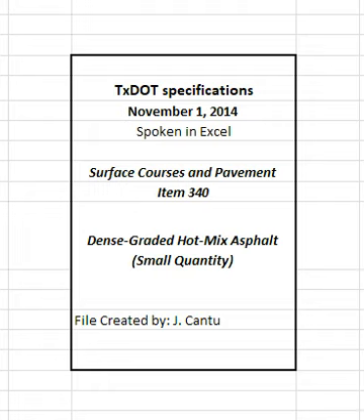If the engineer determines that the irregularity will adversely affect pavement performance, the engineer may require the contractor to remove and replace, at the contractor's expense, areas of the pavement that contain irregularities and areas where the mixture does not bond to the existing pavement. If irregularities are detected, the engineer may require the contractor to immediately suspend operations or may allow the contractor to continue operations for no more than 1 day while the contractor is taking appropriate corrective action.